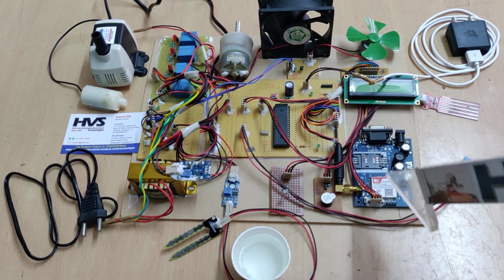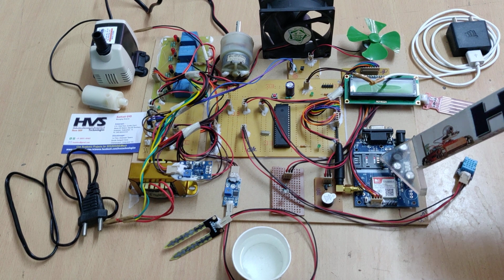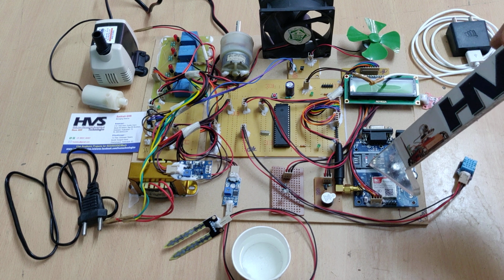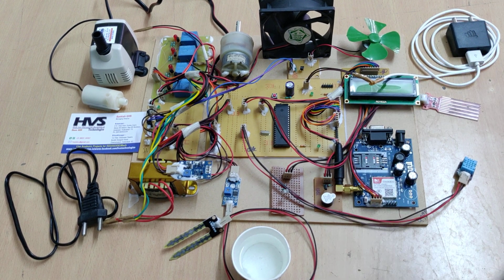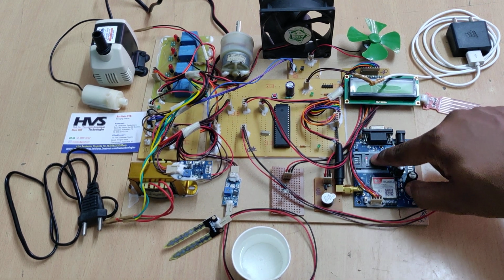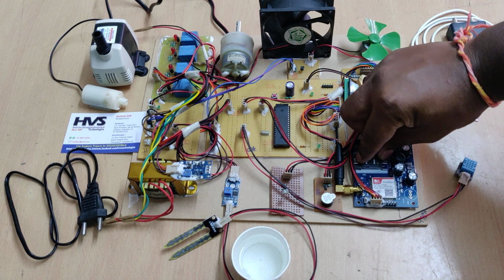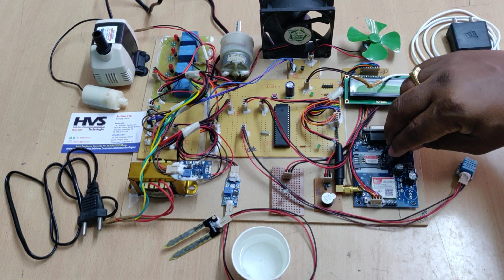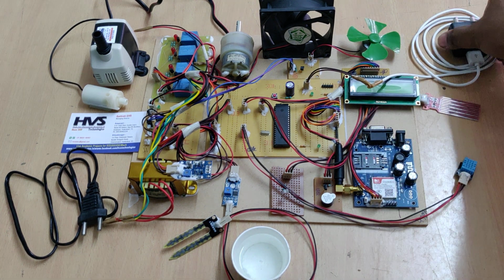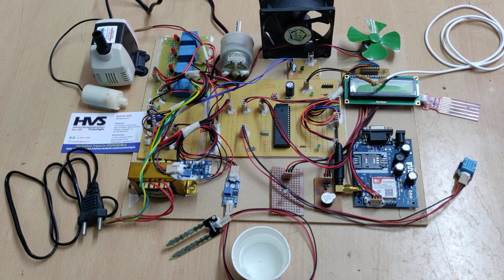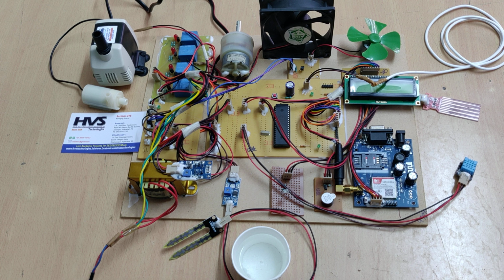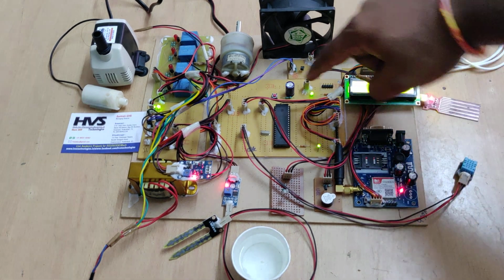Coming to the execution process, before switching on this kit we need to insert a 4G SIM other than Jio. It is better to use Airtel, Vodafone Idea or BSNL. You should have main balance or SMS balance, and you should have validity. Insert it properly according to the notch over there, so that the 6 pins are connected to the 6 pins of the SIM card. After inserting that, provide the power supply for the motherboard, provide the power supply for this transformer, and now switch on the kit. Once you switch on the kit, hold this reset switch.